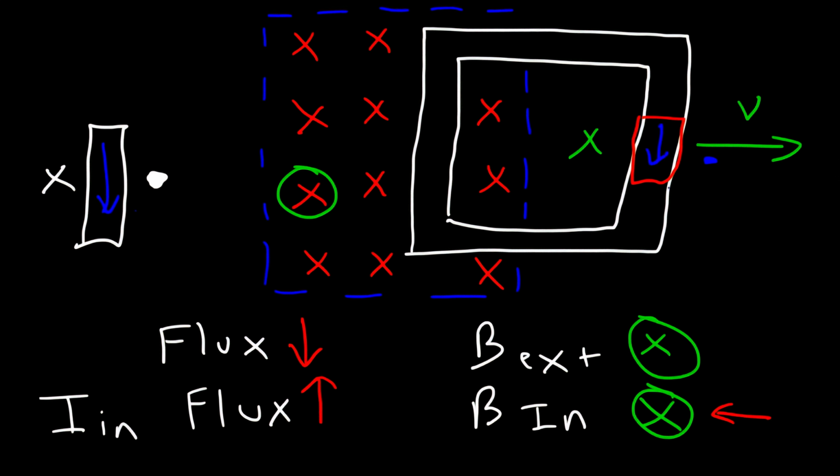So if it's traveling down here, then it's going to be to the left, and on the left side, it's going up, and at the top, it's going to the right. So therefore, it's traveling in the clockwise direction, which makes sense. As the coil moves into the magnetic field, the current is traveling in the counterclockwise direction, and as in this example, as it moves away from the magnetic field, it's going to reverse, traveling in a clockwise direction. So you have to be careful with every step. Hopefully these 3 examples give you a good idea of the process that you have to use in order to determine the direction of the current.